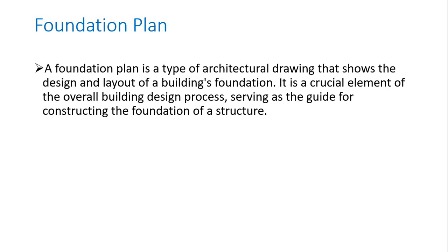The foundation plan. Civil engineers are concerned with it. They have to make a separate foundation plan. For example, if we are working on a 2 to 3 story building, we shouldn't require this foundation plan, because we can simply make a foundation. But if you are working on a building more than 10 stories high, you have to check the soil bearing capacity. You have to make a deep foundation.